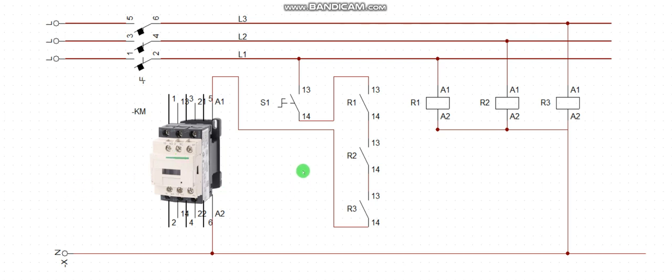So that is the essence of preventing that incident by using phase failure. It is part of the protection that an induction motor requires. So if you cannot access the phase failure as a complete component, you can use your relay components to customize your own phase failure. So this is the arrangement.